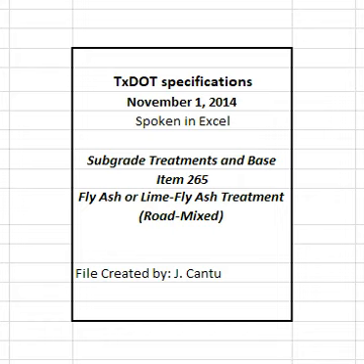Before final acceptance, the Engineer will select the locations of tests in each unit and measure the treated depth in accordance with Tex-140-E. Correct areas deficient by more than 1/2 inch in thickness or more than 1/2% in target lime or fly ash content by adding lime or fly ash as required, reshaping, recompacting, and refinishing at the Contractor's expense. Rework, recompact, and refinish material that fails to meet or that loses required moisture, density, stability, or finish before the next course is placed or the project is accepted.